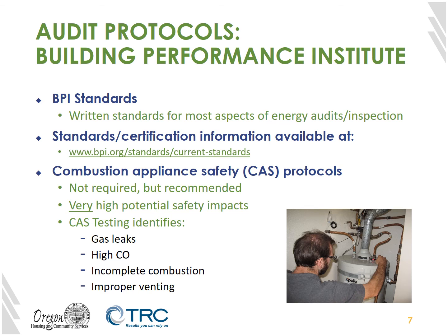Although these systems are relatively uncommon in Oregon, and so this testing isn't required, it is strongly recommended due to the potential health and safety ramifications of improperly functioning systems. Gas testing will look for gas leaks, high levels of carbon monoxide, incomplete combustion, and whether a system is properly venting its combustion gases or spilling them into the living space.